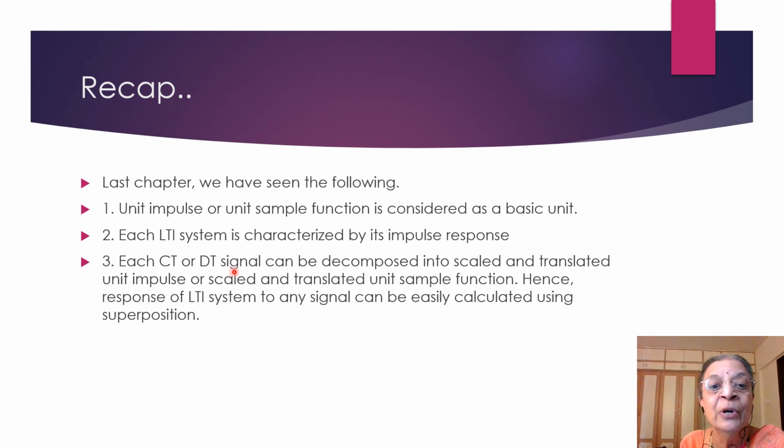And then, to calculate the response of the LTI system to any signal, we decompose the signal into scaled and translated unit impulse, or scaled and translated unit sample function in case of discrete time signals, and then we can calculate the overall response by using the superposition principle.